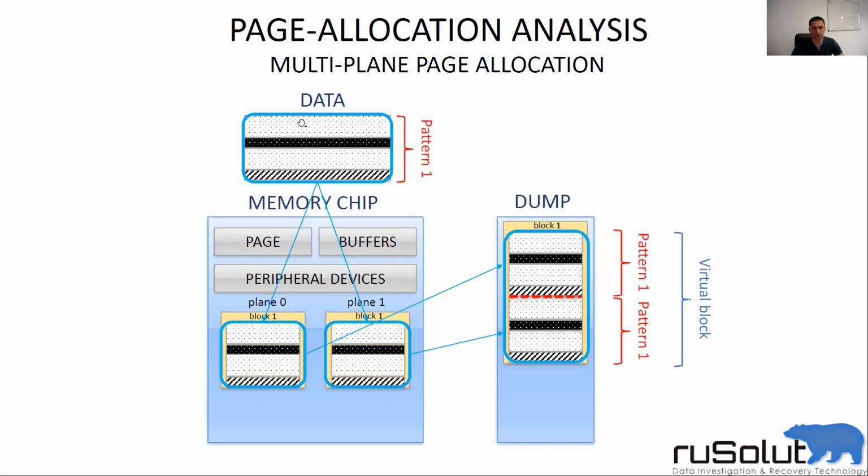And if we have a look at this bitmap, we will see in the beginning this type of pattern, then some line, then again this type of pattern, and then some diagonal lines. The thing is that data looks like patterns, right? If you scroll the bitmap, you will find different patterns. So user data looks like patterns. Unless this is some archives, zip files or video files, pictures, even pictures may have some patterns. I mean, you can see some lines between pictures. But anyway, almost all flash devices will have some recognizable patterns of user data. And let's say that this recognizable pattern is going to be written into the memory chip.